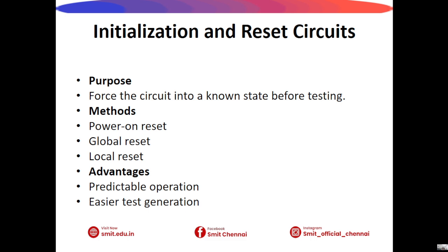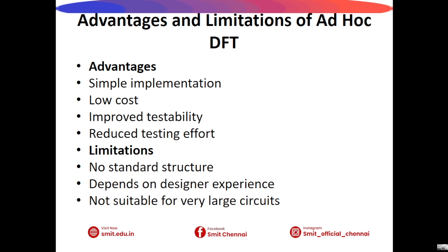Next, we see about the advantages and limitations of ad hoc DFT. Ad hoc techniques are attractive because they are simple and inexpensive to implement. They improve fault detection and reduce testing effort. However, they are not standardized and rely heavily on designer expertise. As circuit complexity increases, structured DFT methods become more effective.